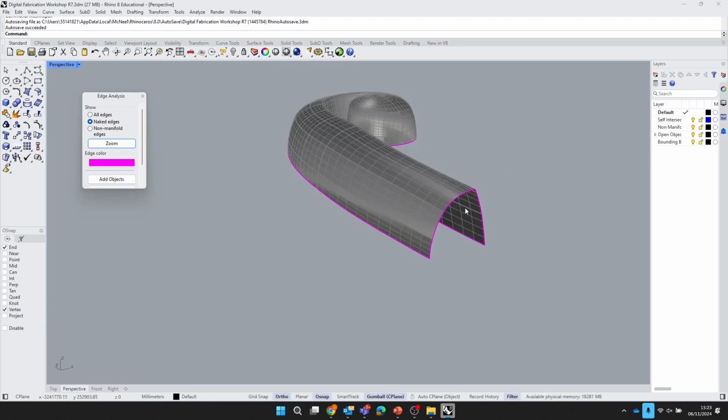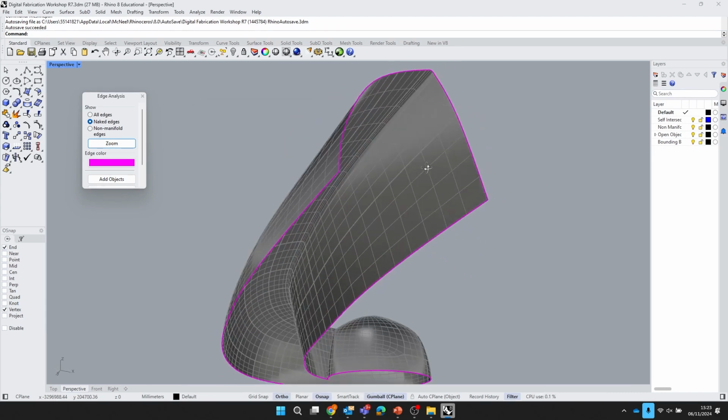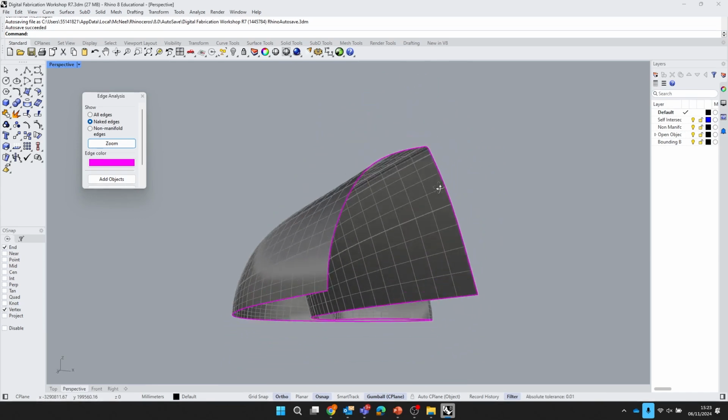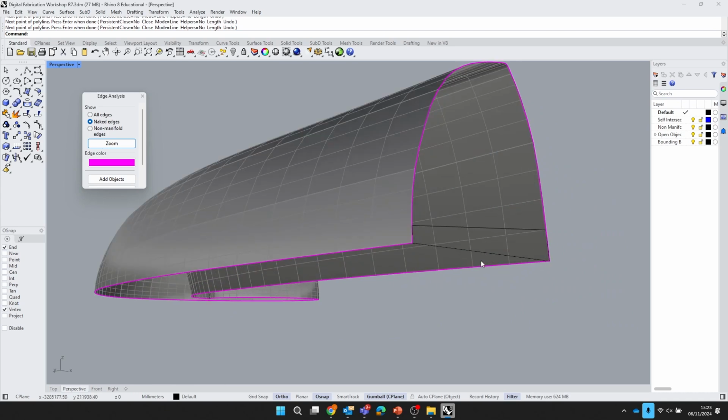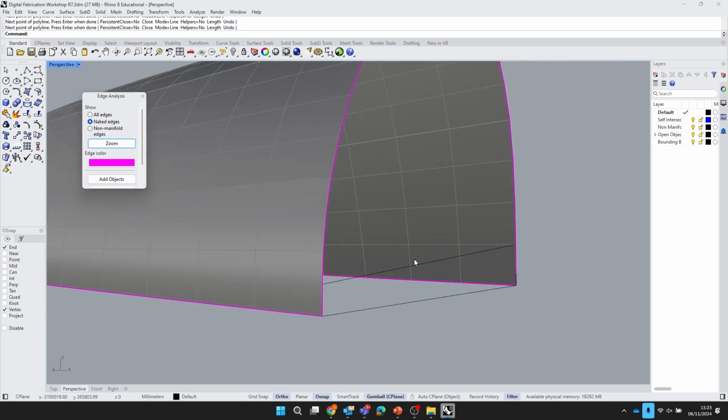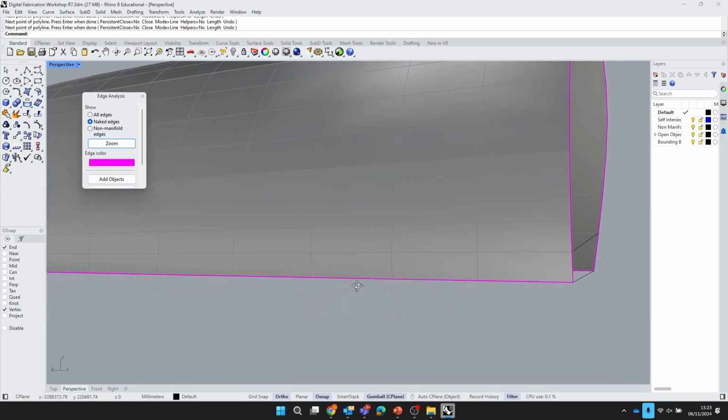Now, do I need to manually draw every single face? God, no. Of course not. Hell no. All I need to do again is find a common edge where those planes change. So we've got this one on the XY plane underneath the object, this one on the XZ plane. And again, all I would do is make a rectangle between those points. Make sure you're snapping to the vertexes, something like that. Bit hard to see in this colour. You see I'm snapping almost like to the grid.